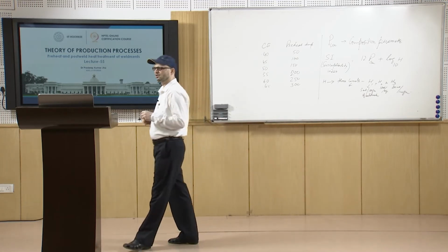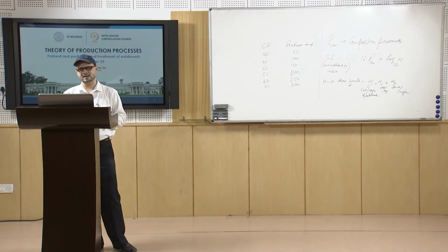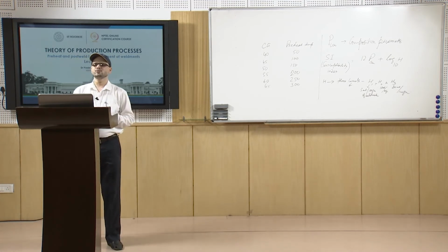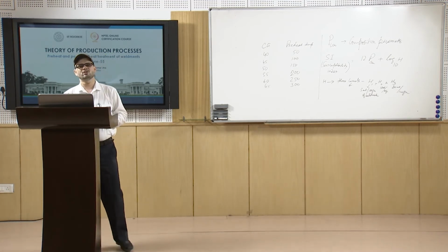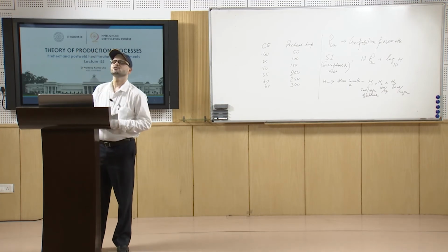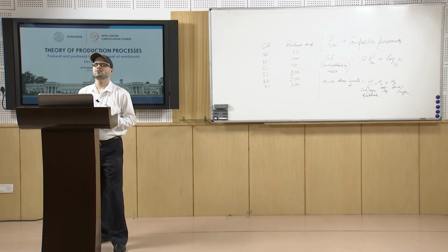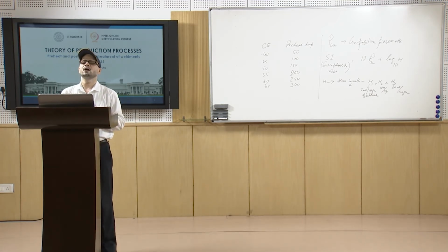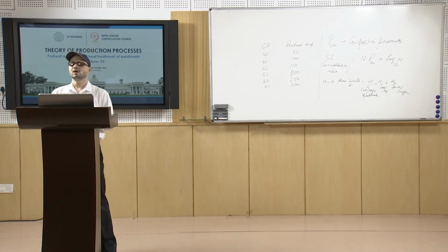With some restraint, there can be distortion or cracking. So, when the plate has a thickness of more than 6 mm, you require preheating to a temperature of about 150 to 260 degrees centigrade. That is the requirement in the case of aluminum.